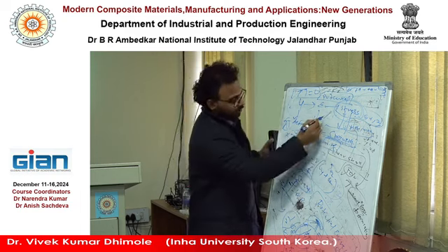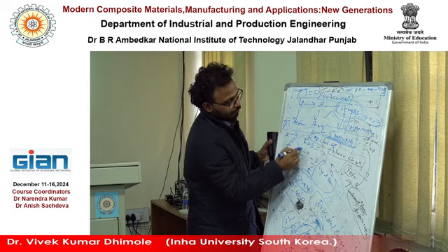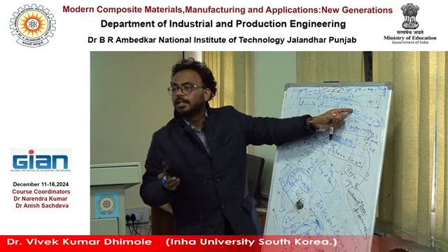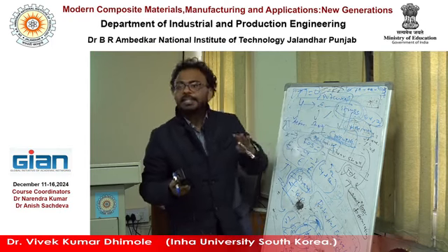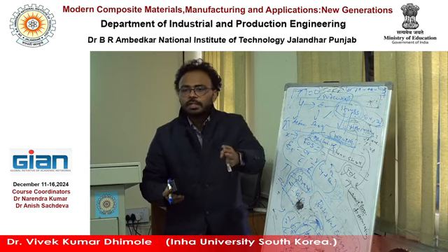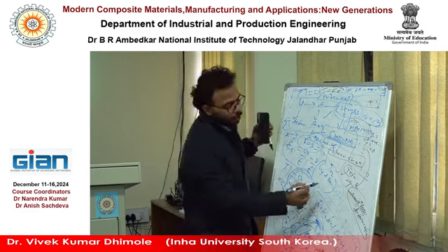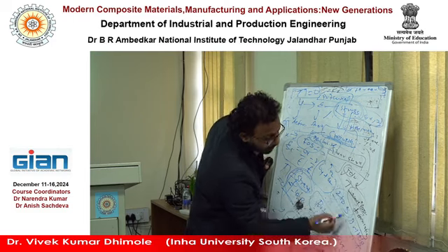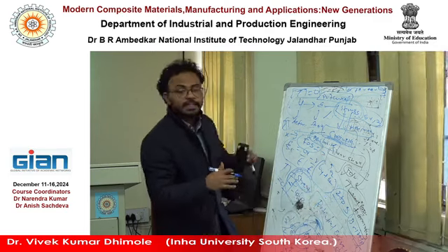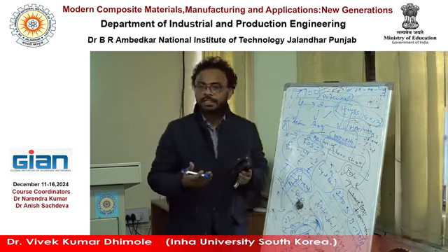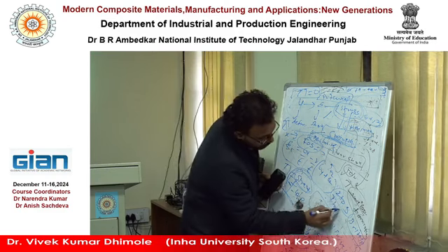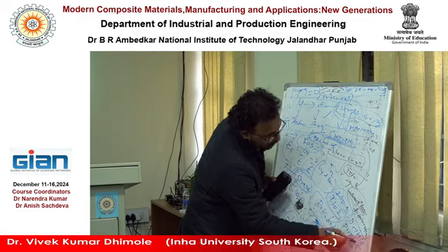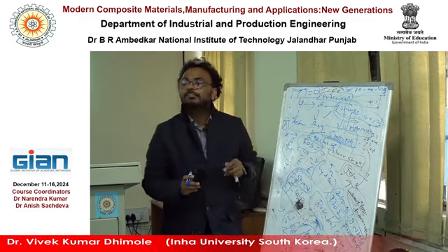From there we reach the factor of safety: how much below the strength is our calculated stress, 2 times or 3 times? For brittle material, we need approximately 3 times because they have sudden failure. So we need a factor of safety between 2 to 3 for brittle material. But when we design with ductile material, because it has ductility, we can go with a factor of safety of 1 to 2. So this is the way to calculate and design things by FEM.